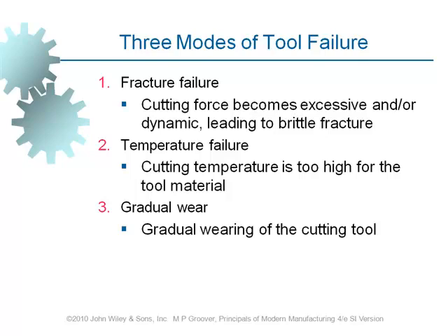And number 3, how can we increase the lifetime of the cutting tool to make it last longer when we are referring to gradual wear? Again, by lowering cutting speed and feed rate as much as possible, we can increase the life of the cutting tool.